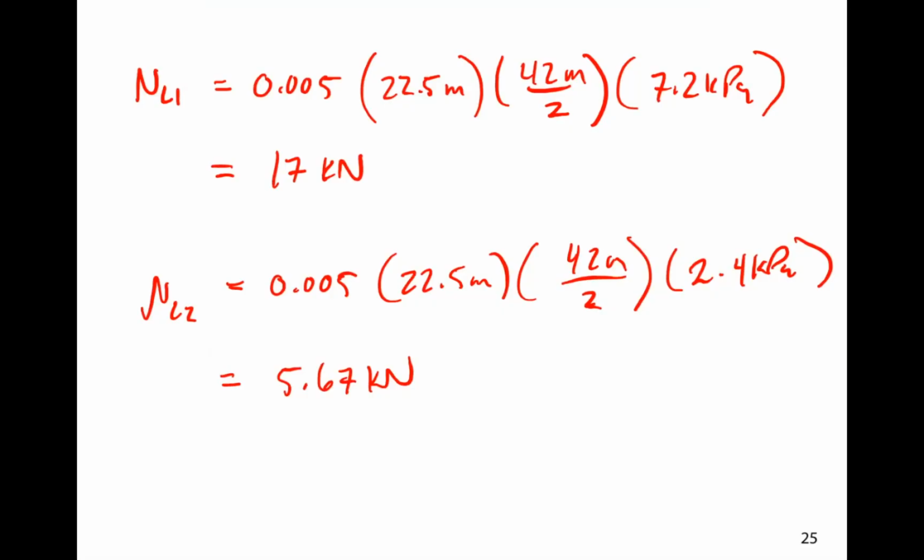Any questions about where those two numbers come from or what they represent in terms of an equivalent lateral effect from those gravity live loads on the floor? Is that a hand? Yeah. That's a great question. Live load reduction factor. What do we do for that? The first thing is neither of these spaces can have the live load reduced, but if they could, I'll give you the right answer in lab. So what I would say for now is do not reduce them for notional lateral loads.